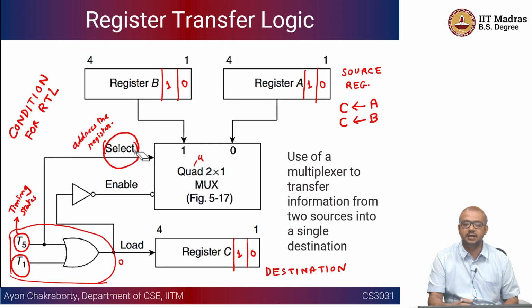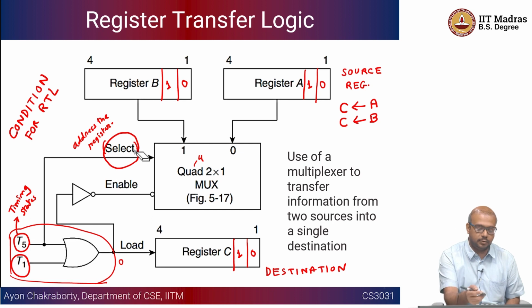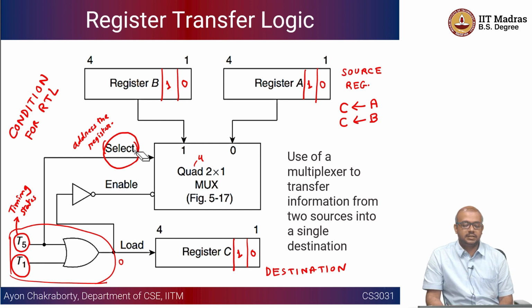You are encouraged to think about it. That will give you a lot of clarity. So the exercise that you must do is to have a very small circuit using multiplexers. You don't have to worry about all this enable and so on. All you have to do is that there is a set of conditions. There are three steps to do the swap, as you know, and I'm not going to repeat that. So there are three register transfers and they are strictly ordered in time.